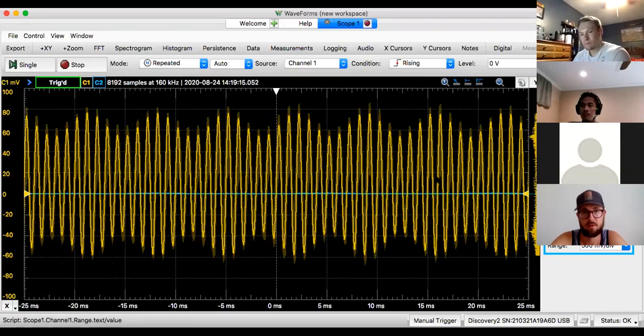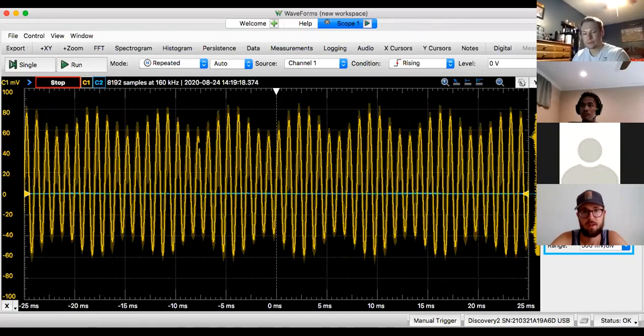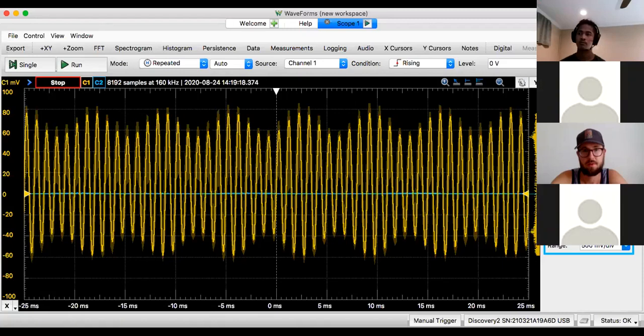If I freeze that, that means for every one of those sines, you have 10 of those sines, right? This has 10 cycles for every one cycle of envelope. We call it the envelope. So one envelope, you have 10 carrier cycles.